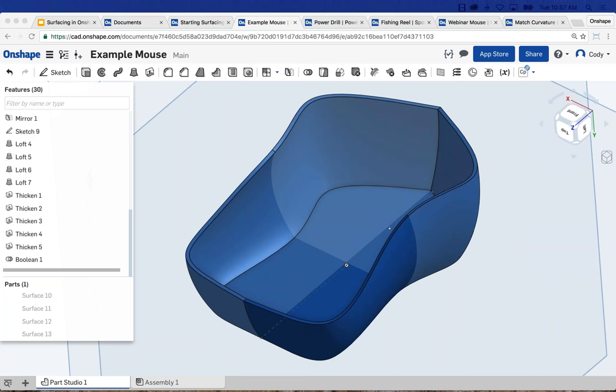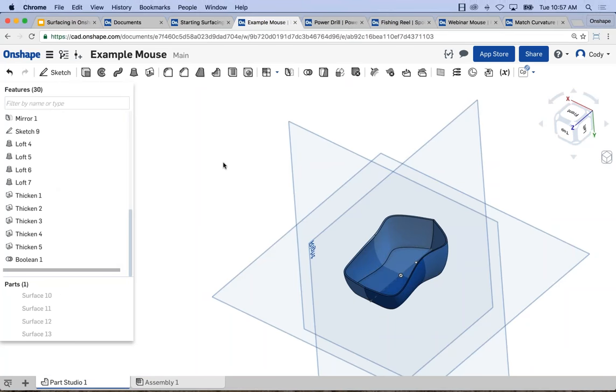Can you patch surfaces? The command I would use in that situation would be a loft, and you loft between them. Could you overlay a solid block on this surface and then split the block with a surface model? Yes, you can split with a surface model. You can also extrude up to the surface, and that's the common technique I've seen. If you have an enclosed volume, do a convert or even an intersection curve and extrude that up to surface. That doesn't work in all situations, but it is an option, especially in an example like this one.